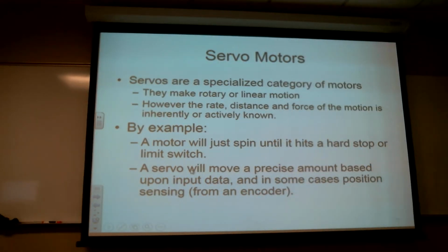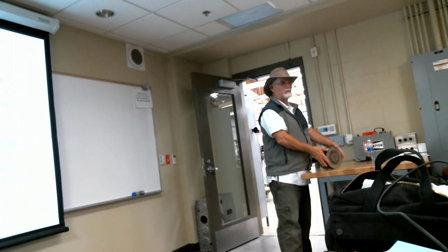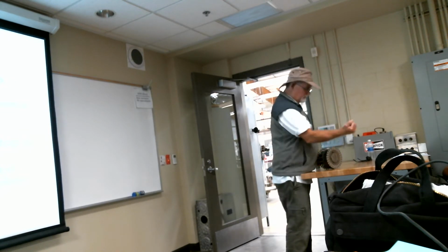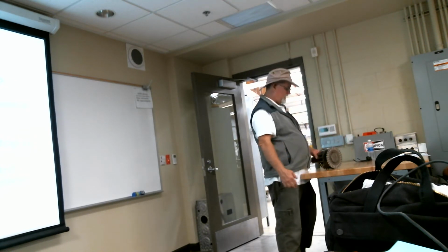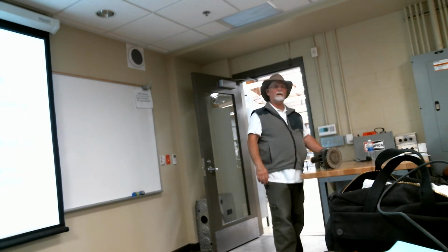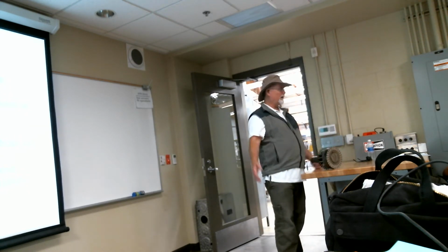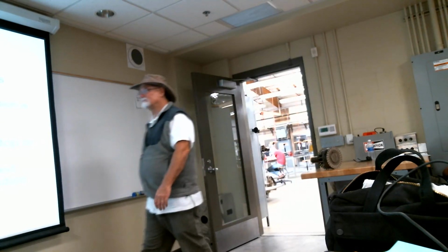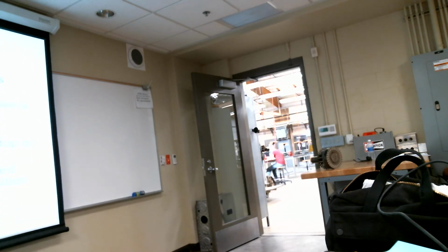I'm going to take this, which is just a big metal shaft, put a bunch of these little plates on it, an aluminum fan end cap, and then shove some bars down in it to clump them together and fuse them into the end caps. A couple of bearings, it's done. It'll spin, it'll work. Conceptually, they're a little confusing, but in the real world, they're pretty easy to make.